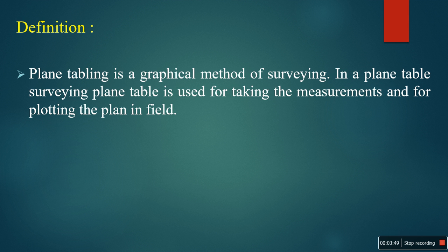At the same time, plotting of the plan or map as well as collecting the measurements in the field will be completed. Later, coming to the office, you can make the drawn plan a perfect sheet. So this is the main advantage of plane table surveying. That's why it is called plane table surveying.